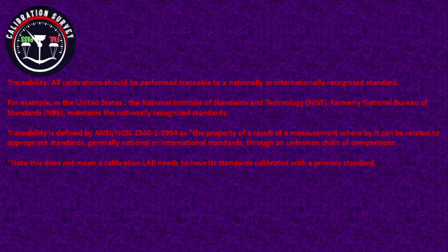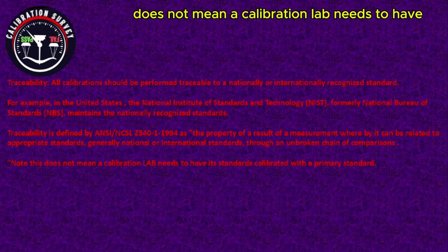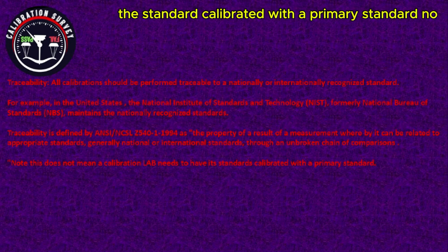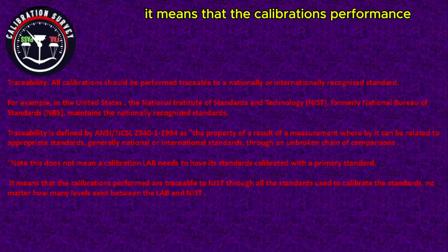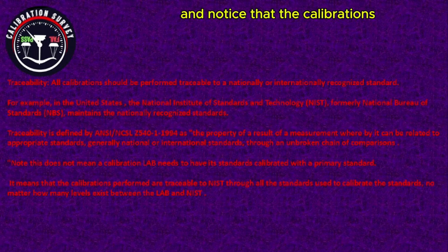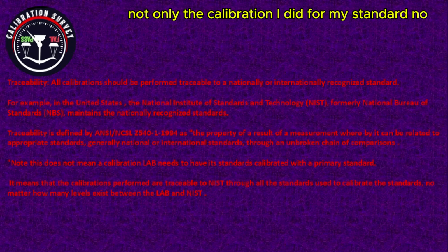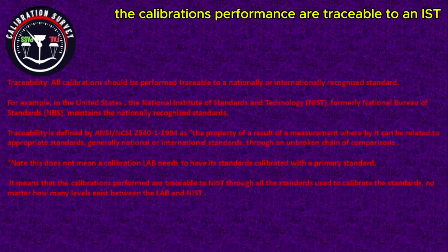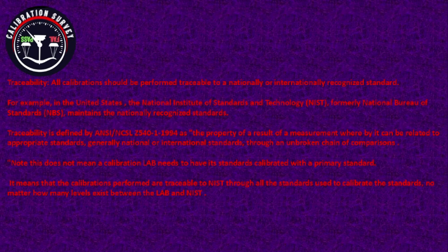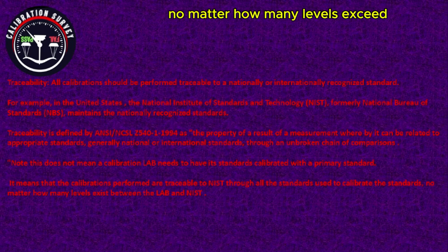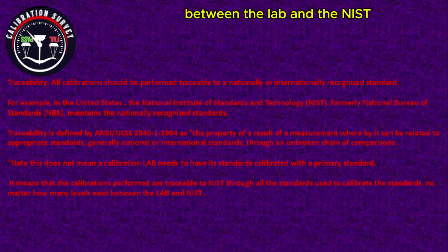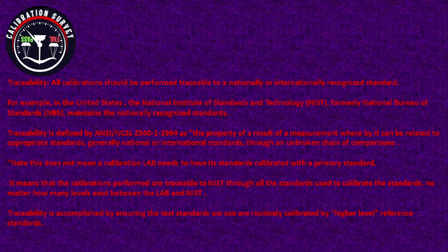And note, this does not mean a calibration lab needs to have the standard calibrated with a primary standard. No. It means that the calibrations performed, and notice that it is the calibrations, not only the calibration I did for my standard, are traceable to NIST through all the standards used to calibrate the standard, no matter how many levels exist between the lab and NIST.